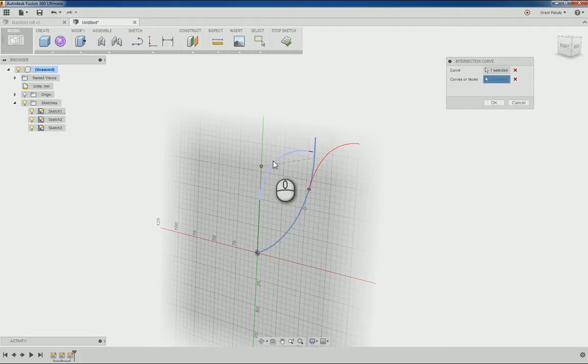So basically all we're doing now is bringing that curve across and tying it into this curve at that point. That's that sort of radius where the fillet starts. If I turn that one off, click there, it doesn't bring it across. So this is the only way I've been able to get intersection curve to work. Like I say, ideally this all should be one line.